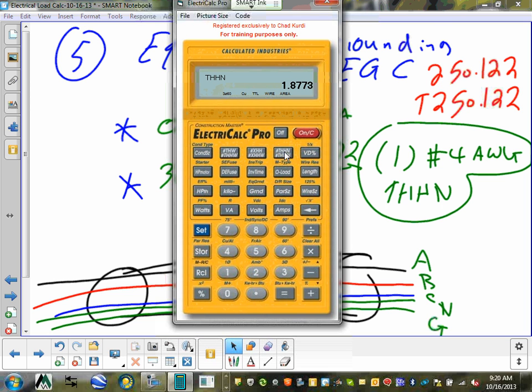This is my total. Can you guys see that? All my total, that's in square inches. And then you go right to the conduit and it gets you 2.5 EMT conduit. Right here, 2.5 EMT conduit. Cool? Now you guys have this calculator, you can use it on the test too, or you're going to use the calculation.